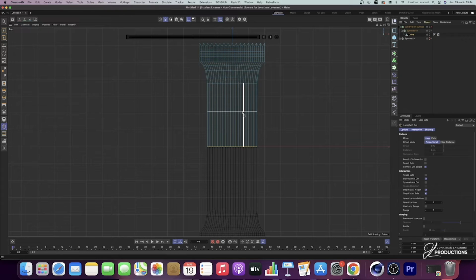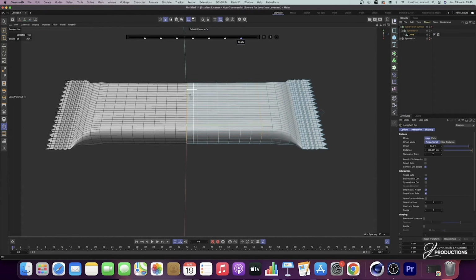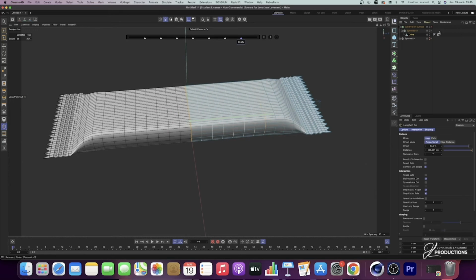I'm going to press Ctrl+R to be able to add loop cuts. So there, it's in order to always have squares. So I'm going to put one in the middle here, and I'm adding several subdivisions here. So there you go. I think it's not bad like that. We have squares of more or less the same size throughout our geometry, so okay.